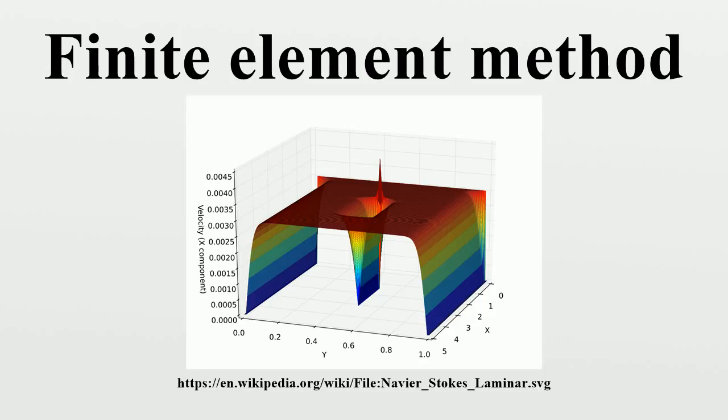FEM is best understood from its practical application, known as finite element analysis. FEA is applied in engineering as a computational tool for performing engineering analysis. It includes the use of mesh generation techniques for dividing a complex problem into small elements, as well as the use of software program coded with FEM algorithm. In applying FEA, the complex problem is usually a physical system with the underlying physics such as the Euler-Bernoulli beam equation, the heat equation, or the Navier-Stokes equations expressed in either PDE or integral equations.